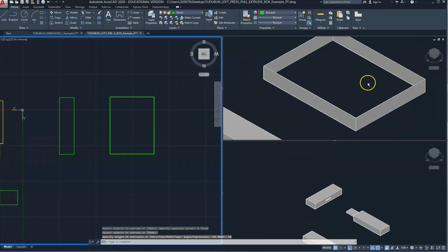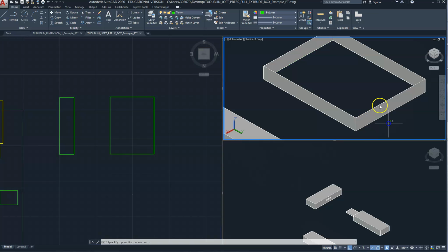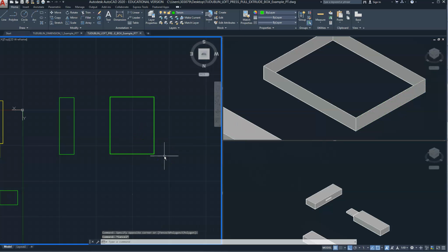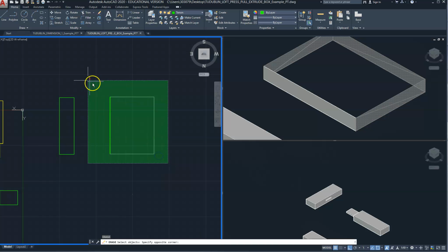What we'll notice is that that doesn't create a face. It just creates four surfaces, and they're actually all separated as well, which is another problem. So if you're getting that problem, it's because you've made lines. So always draw in polylines. So I'm just going to delete that.